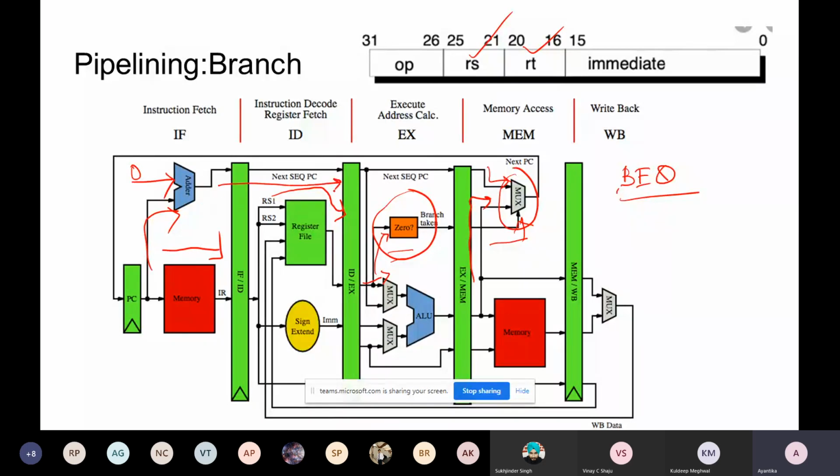See, this is coming out from this adder from here. So these are the two inputs in this mux, and based on this selection line, the selection says yes, that register value is 0. So if it is 1, take the jump. That means now you see your PC is getting updated. This is your PC value, the next PC value is getting updated based on this condition. Mainly this part only decides which instruction your program counter will fetch next. Clear?